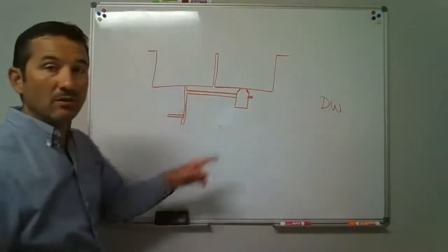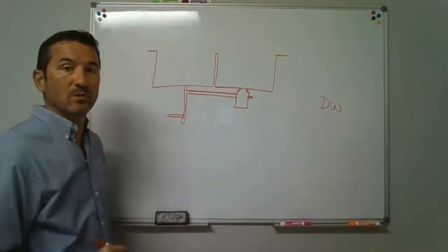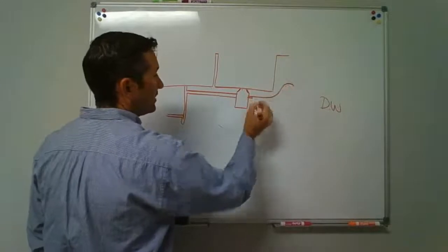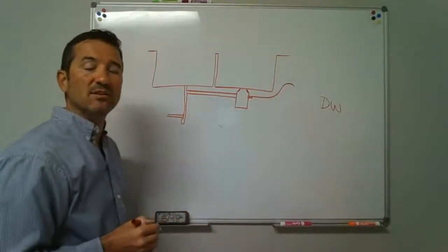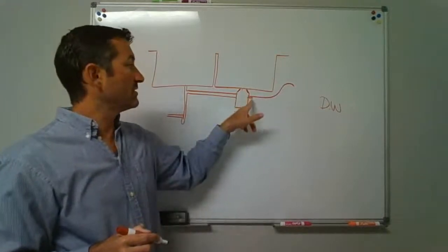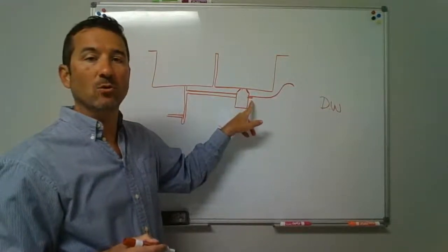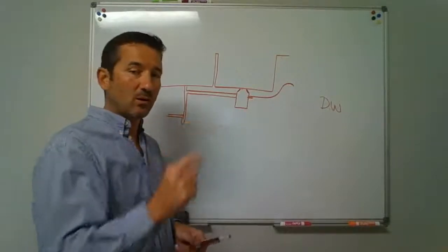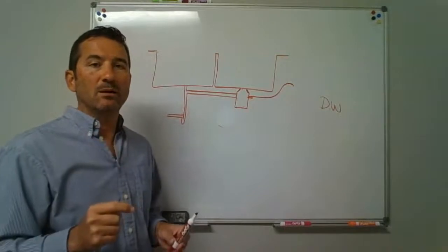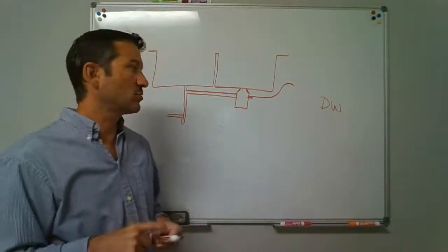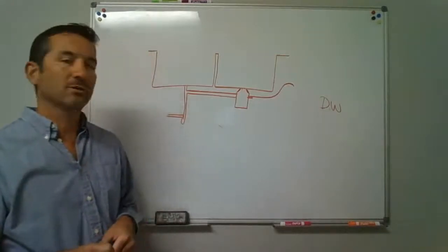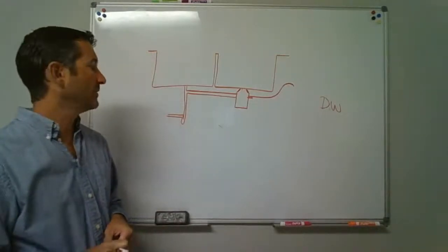Okay, so you have a garbage disposal. Take the little connection on the side. You can take the dishwasher drain hose and hook to the side of that and clamp it to the side there. When you do that, just be aware that if this is new and has not had one to it before, you could stick your finger in the side of that hole and you'll feel a little knockout plug. Be sure to, if you're hooking a dishwasher drain line to it, be sure to knock that plug out before you hook to it. Otherwise, the dishwasher doesn't drain so well.